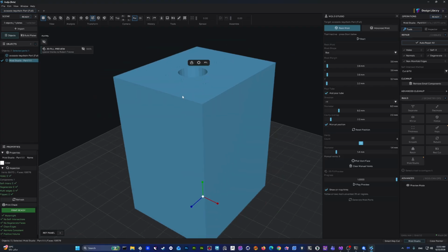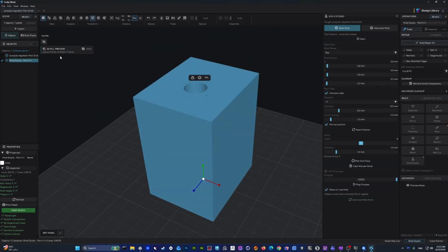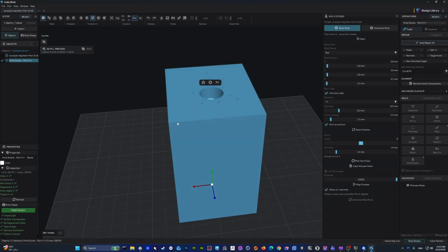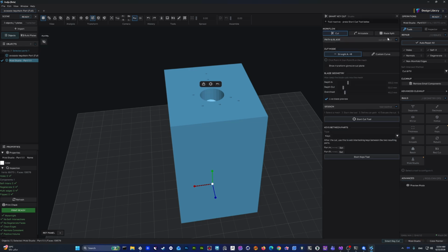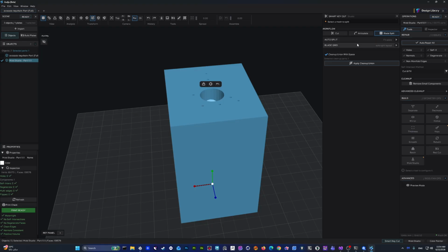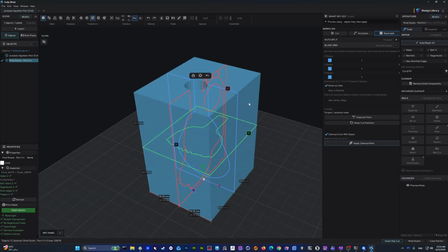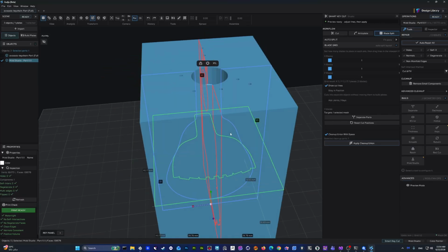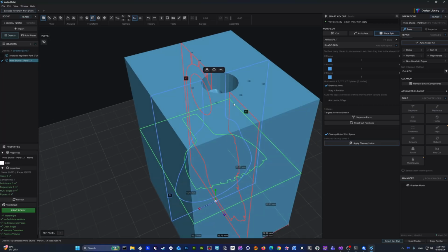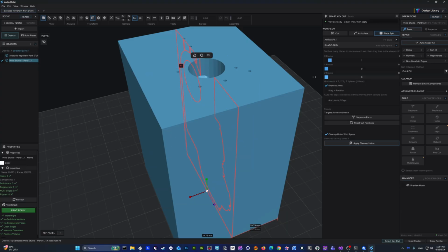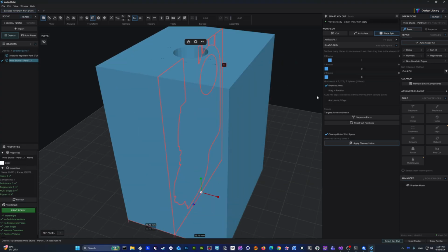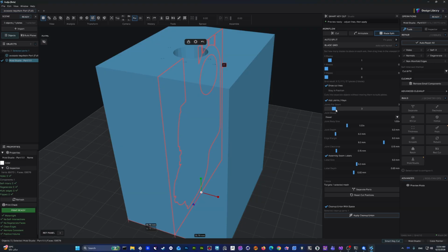first you have a solid mesh, okay, and you want to control the cut, like you want a left part and a right part. So we're going to use a smart key cut to do this, with blade split. And I'm going to go to blade grid, because as I told you, I have full control over how many blades I want. I want only the red part to be separated. So I'm going to make both of these 0, and I want to add joints, make them like 3, maybe 5,